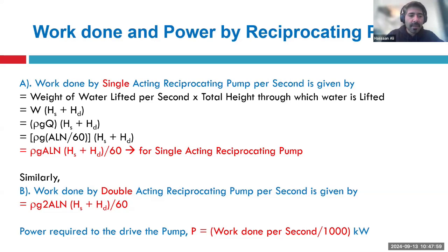The things you can play with are your stroke length, so you can increase the stroke, meaning a bigger or longer pump, or you can increase the diameter of the cylinder, or you can increase the number of revolutions of the system. So when you're considering what type of pump to use, is it basically just how viscous your fluid is and how much you want to pump? Let's start with there. Yes.